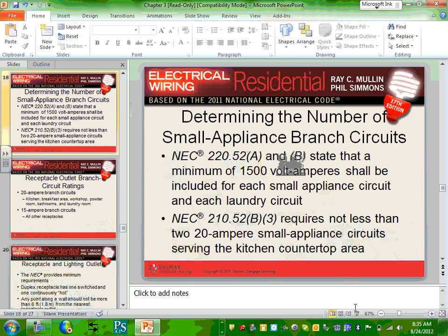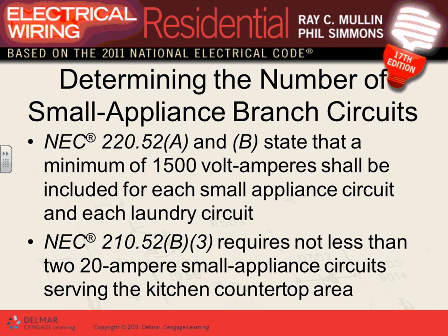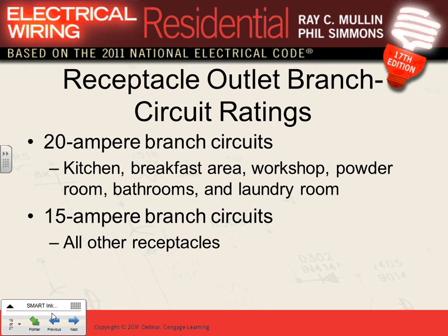Okay, let's just talk a little bit about branch circuits. We're talking in dwelling, so I would like you guys to remember in branch circuits there are 4 types of branch circuits. So you remember that one. 20 amp branch circuits. In the kitchen, here's what you're going to be doing. Required by code, the 20 amp circuit, if you want to write yourself a note.